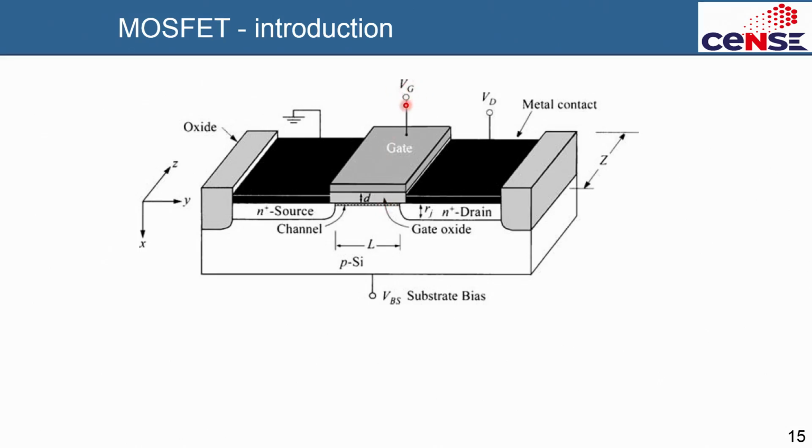So the gate, this third terminal over here, is controlling the current flow between the first and the second terminal. In other words, the voltage difference between the first and the second terminal, between source and drain, is actually not playing a role in the current. It is rather the third terminal which has the ability to make the transistor channel vanish or come back.